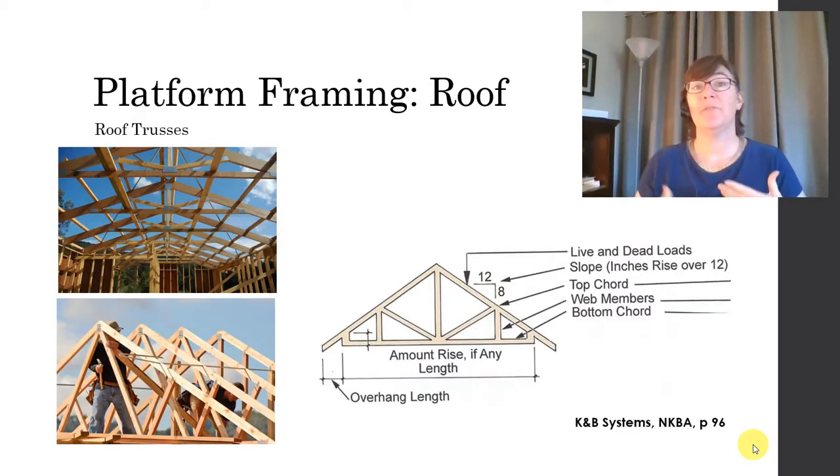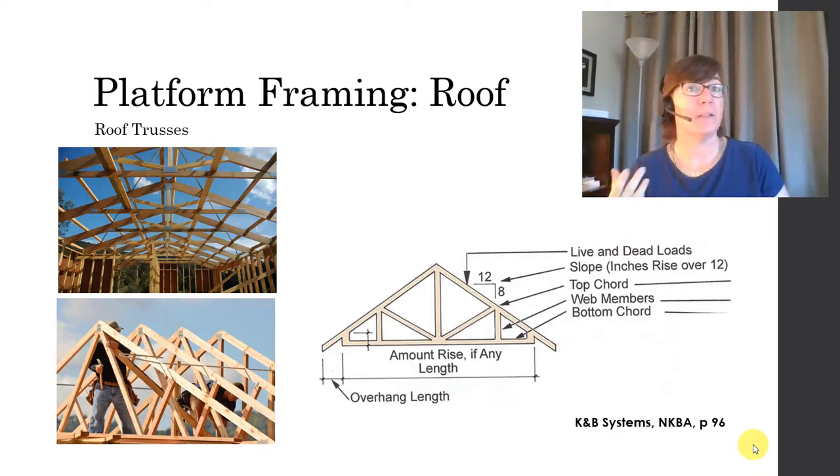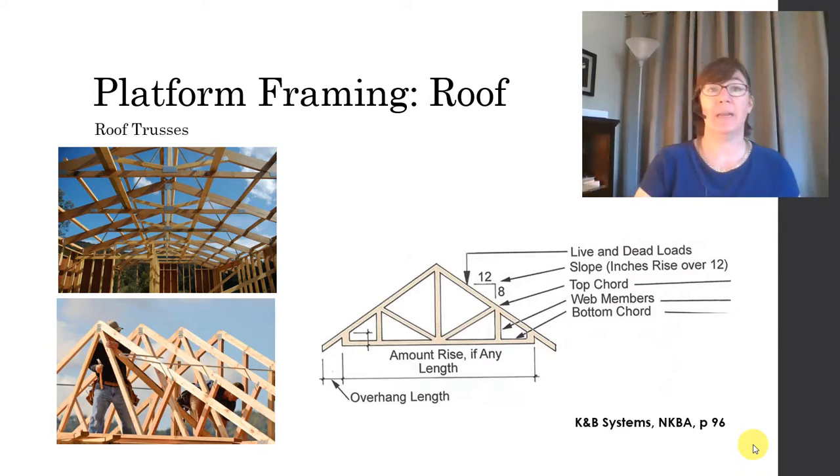Roofs can also be framed by trusses. Trusses are very, very common in residential construction, and often they're less expensive. Why are they less expensive? Because they're prefabricated at the factory. So there is less on-site labor. There's also less wastage of material as each individual rafter is cut.